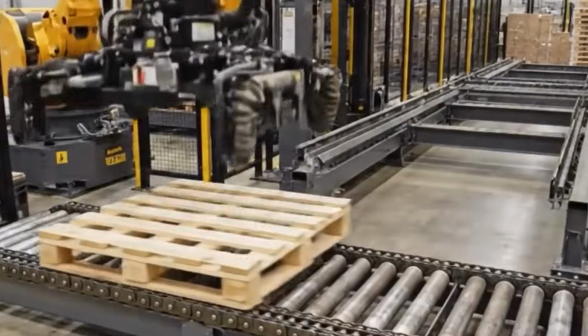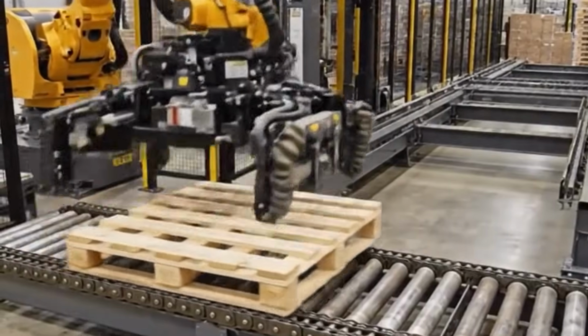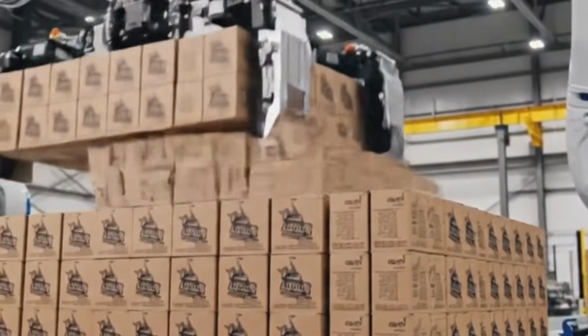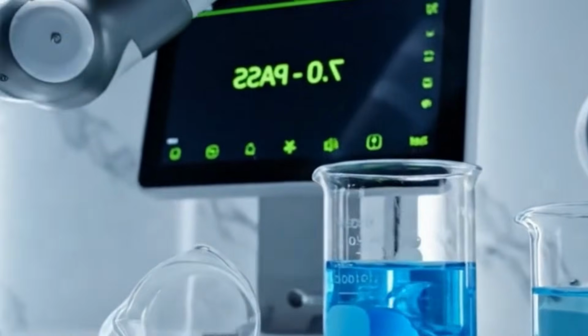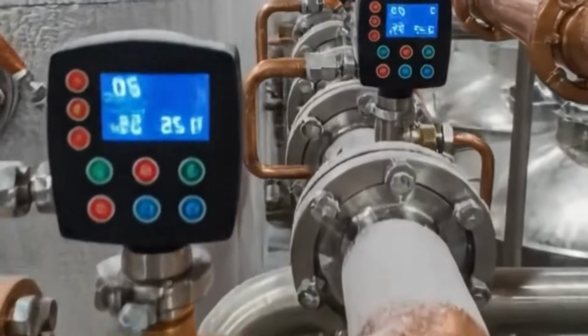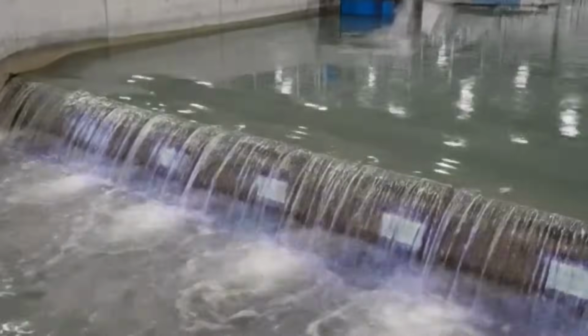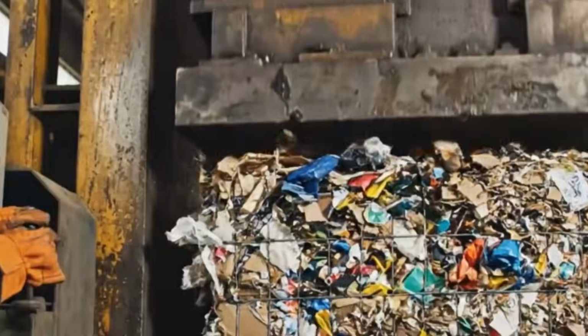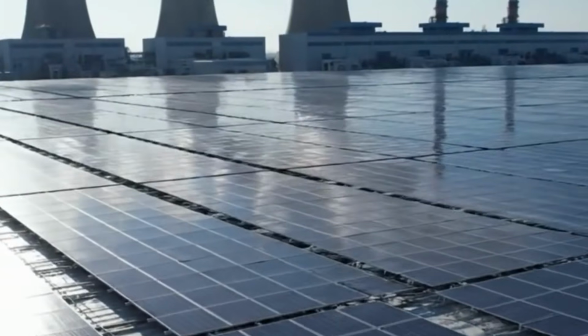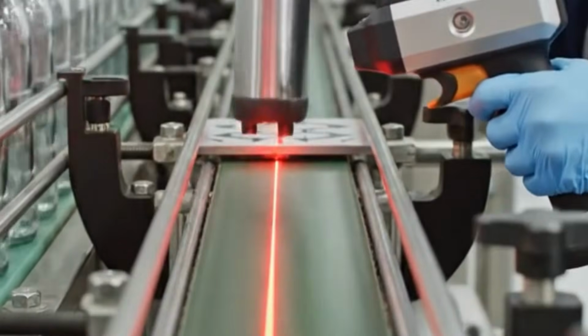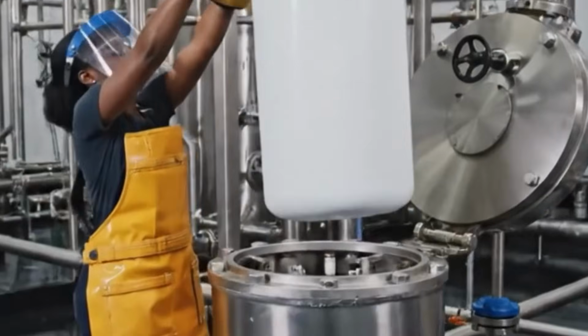Labeled bottles proceed through a pressure-sensitive labeling station. Label spools feed through optical sensors and tensioning arms. Each label is applied to the bottle using rubber rollers or air jets and wrapped around the circumference. Vision systems verify label placement, orientation, and print quality. Optional shrink bands are applied for tamper evidence.